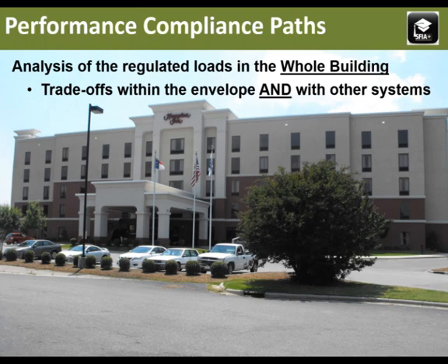The performance options in the IECC and 90.1 can be complex and require someone reasonably proficient with a software simulation model. All of the loads in the whole building are simulated and compared to a standard building as described by the code or standard. We'll focus on a few key points so you leave here knowing about some opportunities to design a more efficient building.